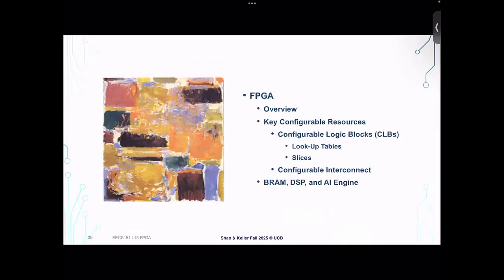Okay, so that's the basics of the programmable fabric in FPGAs. What's happened in the last 20 years or so is that they've started to garner more and more bells and whistles, where basically the FPGA designers were figuring out, oh, these are the common applications that people are running on them, so let's harden those. And by harden, we mean design little blocks of ASIC logic that specifically do certain functions so that you don't have to use up a lot of CLBs to program that function. You can just put it on this specialized hardware.